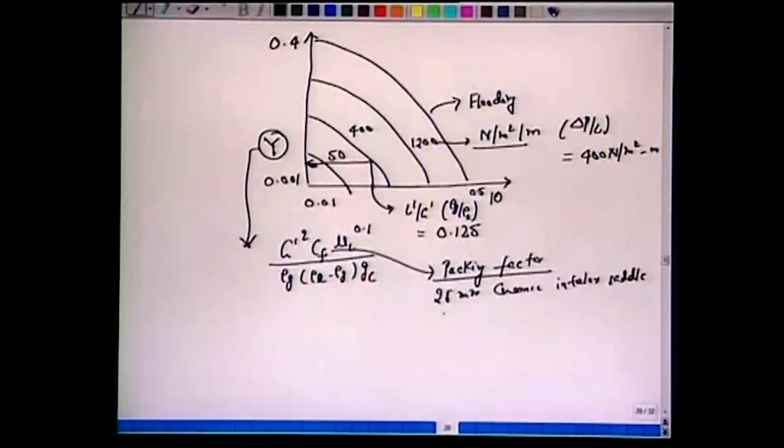So, if you look at one of those tables, you will see the type of packings, the size of the packings, and you will see a factor A, the interfacial area, as well as a quantity Cf, which is a packing factor given by the manufacturer. Take this factor, which would be 98 from the table, and calculate this quantity. If you look at this graph, from this graph, this quantity would be 0.061.